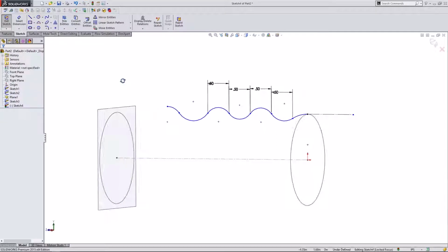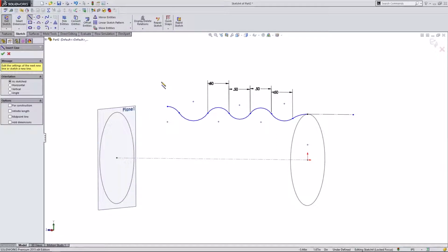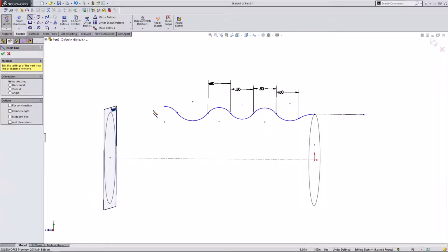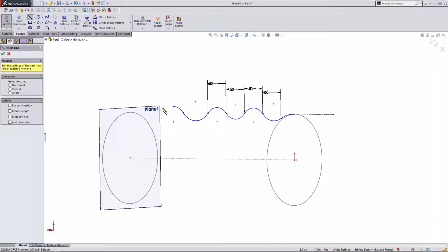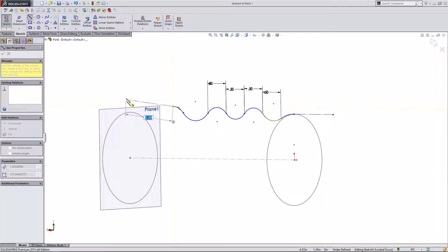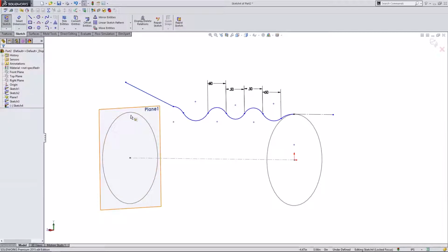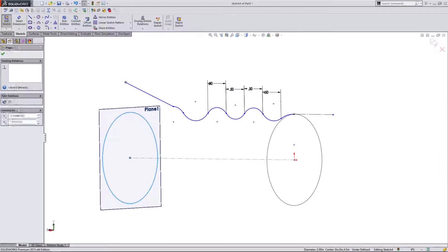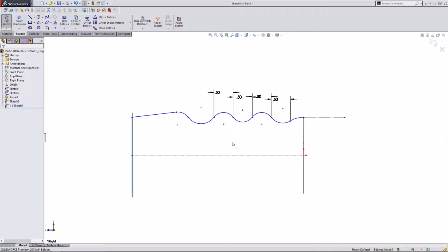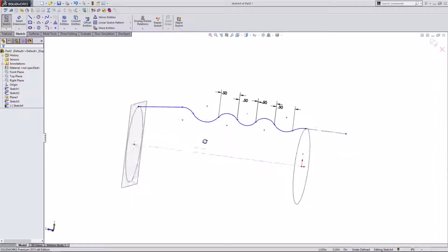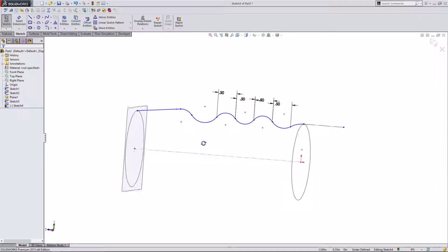on the circle. So to rotate, very quickly, I use the middle button on my mouse. You can also use your arrow keys. You can see that. You can kind of rotate everything pretty effectively. So I'm going to click here, and I'm just going to kind of drag the line out, click on the circle, click on the line point, hit pierce, and you can click on the line and the arc and make them tangent. Okay, great. So that's the general shape I want for this example.